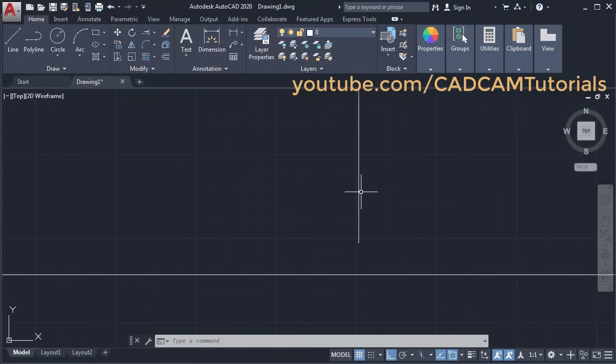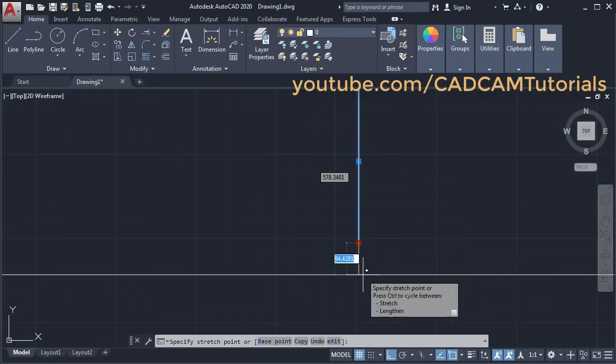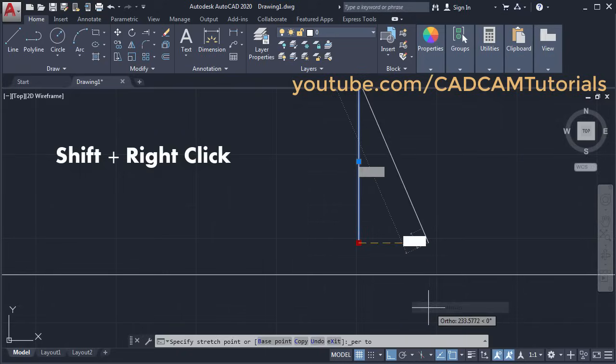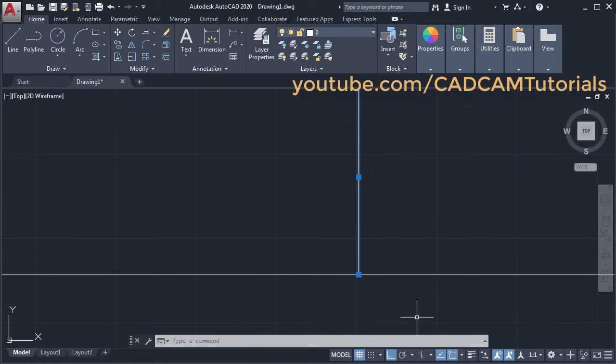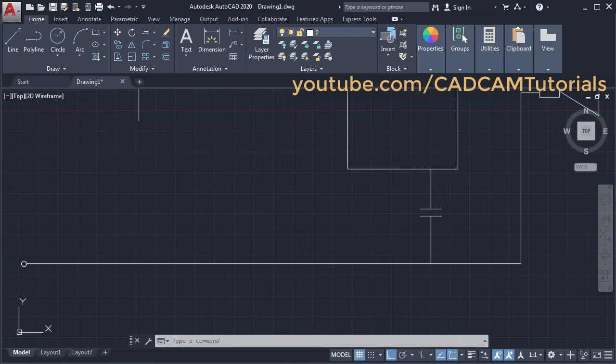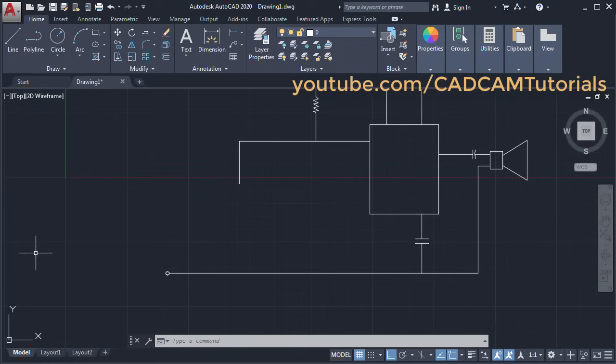For that, click on this line, click on this blue grip, take it below. Then we need to create it perpendicular to this line. For that, press shift plus right click, then click on perpendicular and click on this line. Press escape. So this is ready. Then we need one line here for ground.